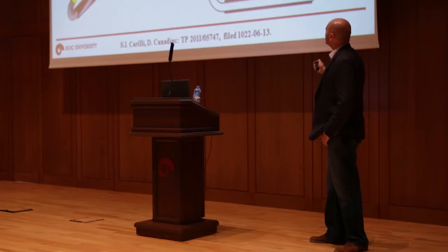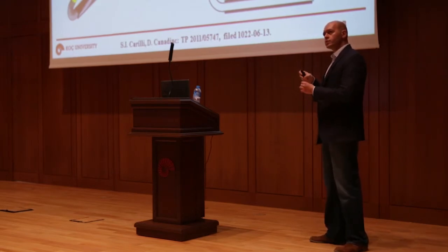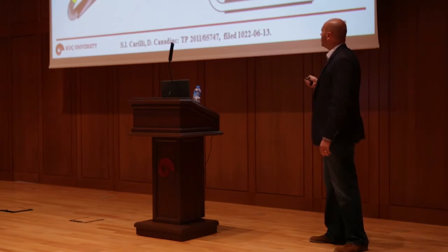So what we do is enter the body using straight tools like these. There is no chance you can do it with classical tools. But we have designed this new surgical equipment such that we make use of the pseudo-elastic property of the material. When the tool enters the body, it's straight, because the ports you have, if you recall from the previous image, are straight ports. When it goes into the body, you can release this tube, which under no loading, under stress-free condition, has a U-turn shape.